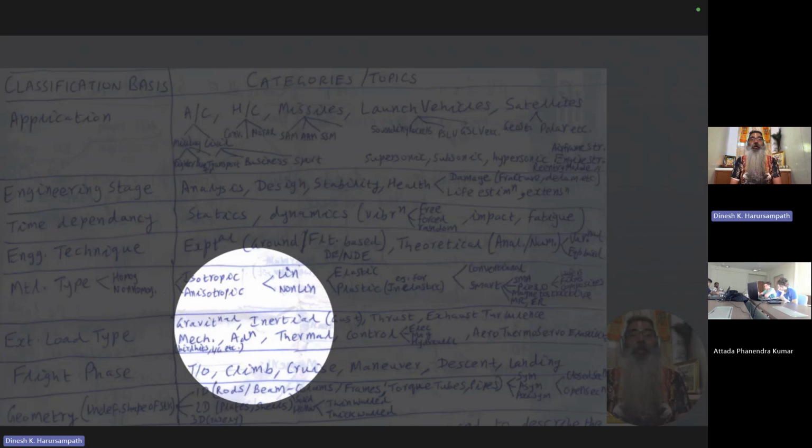That's essentially what is talked about in Newton's first law, where he says that a body in a state of rest remains in a state of rest, or a body in motion remains in the same state of motion, unless and until acted upon by external forces. And forces include, of course, moments and force distributions and moment distributions as well. So essentially, remaining at that status quo is not what is happening here, but there is a tendency to do that, because that is a very basic characteristic of materials, to remain in the state that they were in. When they are subjected to certain forces and moments to make a change, there is that resistance, and the force that comes out of it, usually referred to as the d'Alembert's force, needs to be accounted for in the dynamic model, and that's where your inertial loads come in. They come in the moment equations as well.